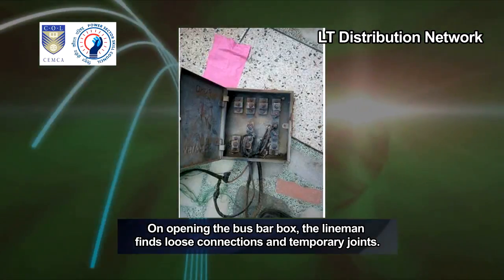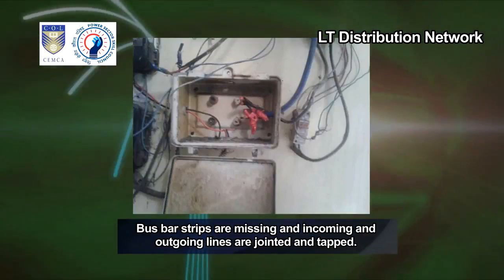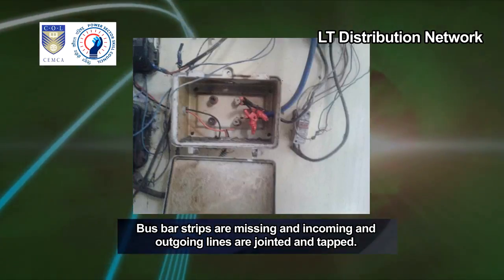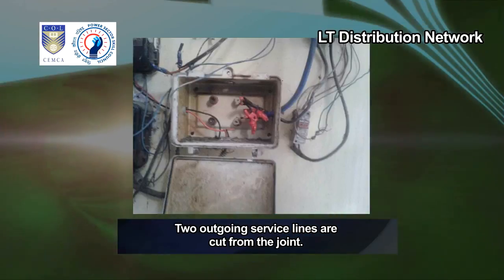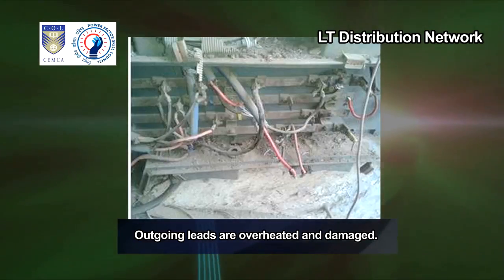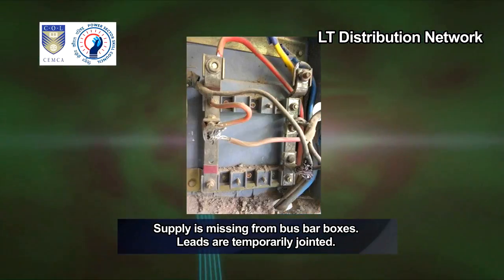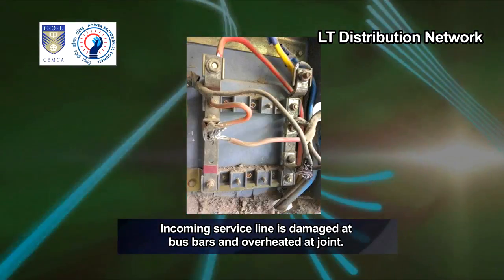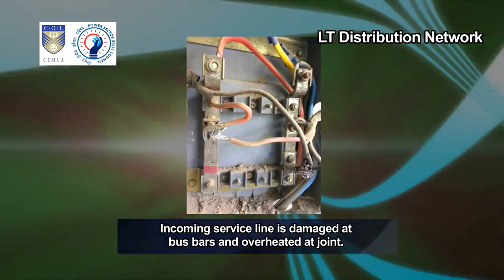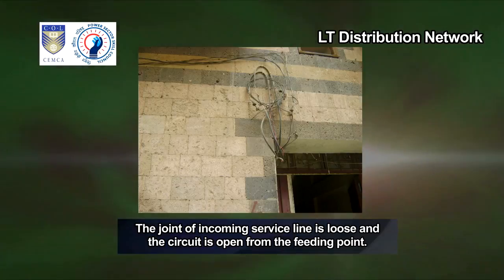On opening the bus bar box, the lineman finds loose connections and temporary joints. Bus bar strips are missing and incoming and outgoing lines are jointed and tapped. 2 outgoing service lines are cut from the joint. Outgoing leads are overheated and damaged. Supply is missing from bus bar boxes. Leads are temporarily jointed. Incoming service line is damaged at bus bars and overheated at joint. The joint of incoming service line is loose and the circuit is open from the feeding point.